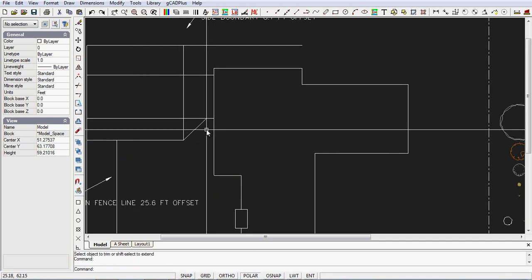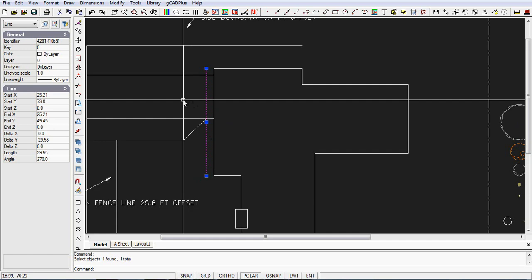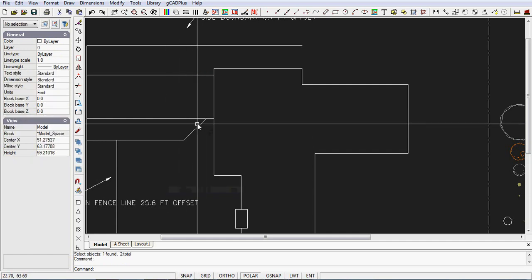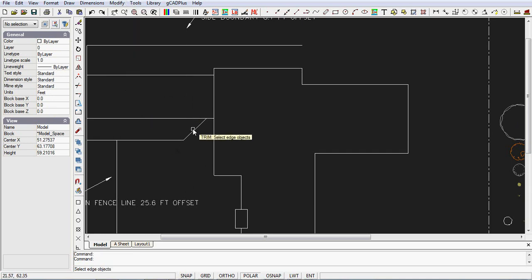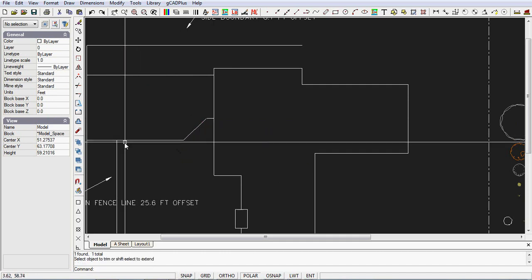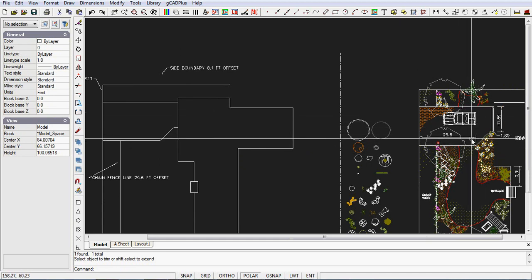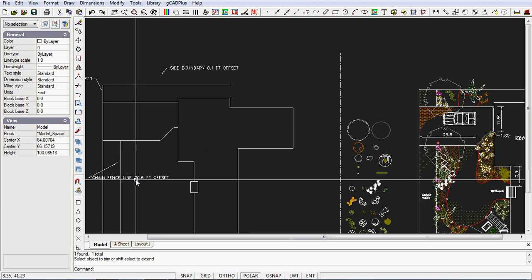And now it comes along there, back into there, into there. So we need to. This line was an offset for a construction line that can be removed along with this line. So we can erase those two, and we just have one last trim to do. So it's modify, trim. This is the cutting edge. This time we knock off the very long piece that's hanging over there, and then unselect all. So now if you compare our model on the right hand side with what we've achieved there, I think you can see that we've achieved it.